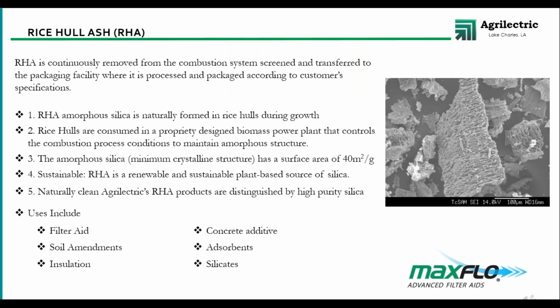Here we get into the byproduct side of the business. I'm not going to get too detailed in this subject, but wanted to highlight that our efforts don't stop at making renewable energy. As you may have noticed the internal structure of the rice hull photo at the beginning of the presentation, when combusted in a controlled environment, what you have remaining is roughly 93% amorphous silica and a 4 to 6% carbon. The photo to the right is a skeletal structure remaining after combustion. The high surface area and non-detect crystalline silica makes the silica unique in certain uses. Listed at the bottom are some of the applications.